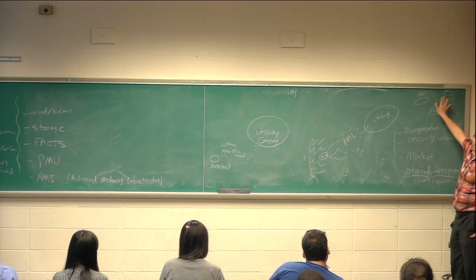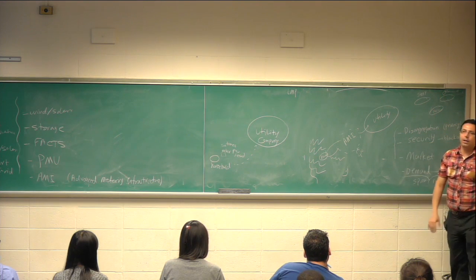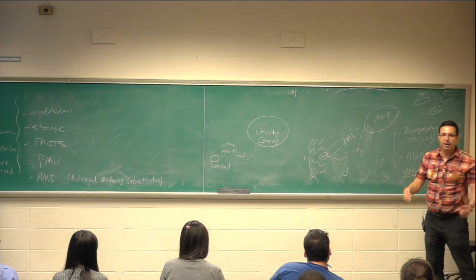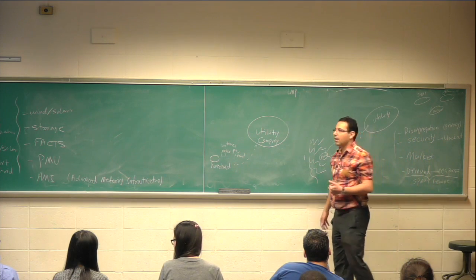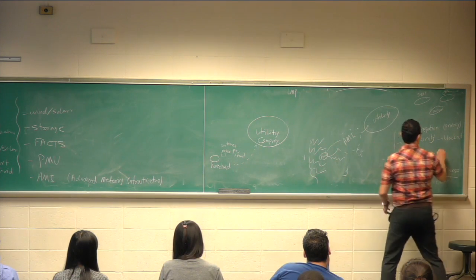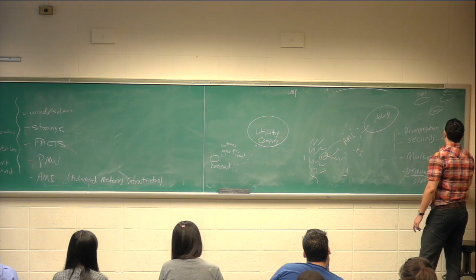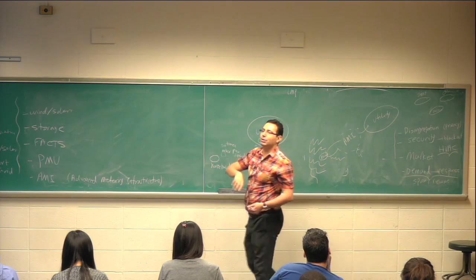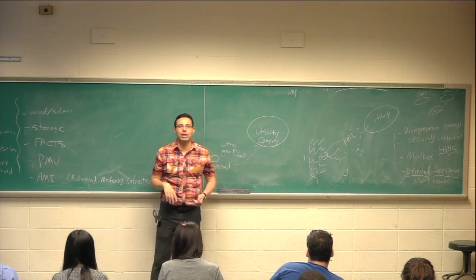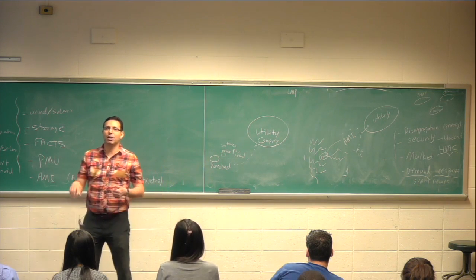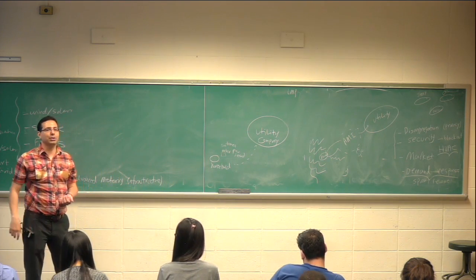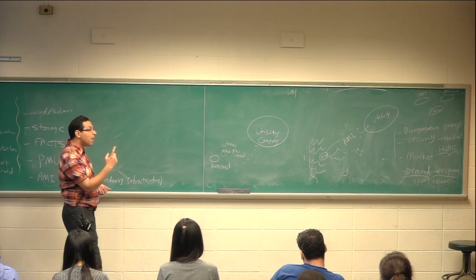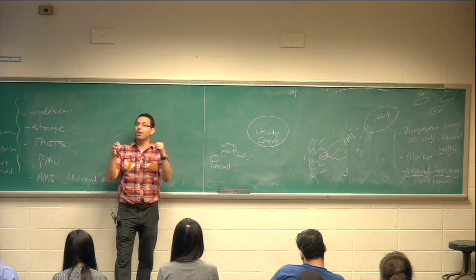This is very costly. We just say, if something goes wrong, I reduce the demand from every consumer who's willing by 2%, and just on certain devices. For example, something very popular is an HVAC device. In places in the world and the US, they're pushing for this. You have an AC, you have a fridge, and the temperature is not really important if you change it by 1%. If you change the temperature in your room by 1%, that doesn't change the comfort zone. It's not important. But if you change the temperature by 1% for a whole city, that's a lot of power.